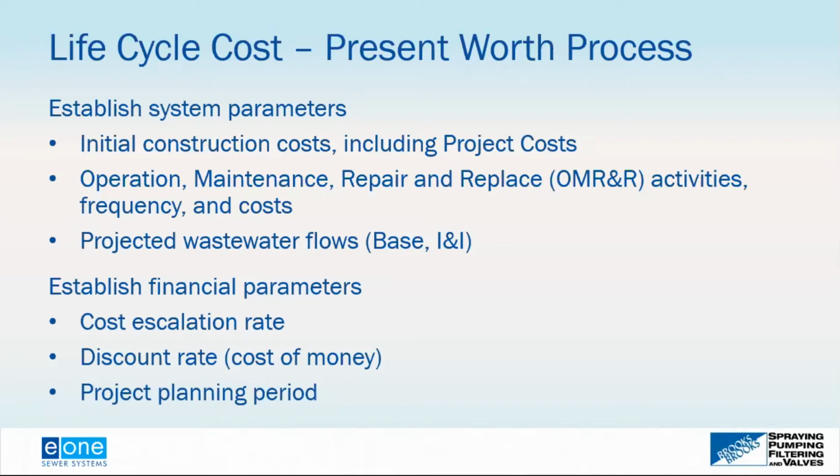And then you want to establish your financial parameters, looking at cost escalation rates, discount rates, which is the cost of money, and then the project planning period, which, as I mentioned earlier, is typically 20 to 40 years. In most cases, that's going to be dictated by the funding agency. You know, if you're funding a project on a 20-year bond, they want to make sure you do a life cycle cost analysis to show it is economically feasible for at least 20 years.